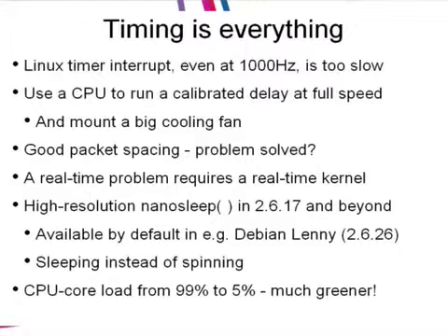And so the real question becomes, what kind of hard real-time kernel do you need? What we really need is the high-resolution timers, so we can sleep for a specific amount of time. We don't really need the hard real-time, where you can interrupt your own kernel.